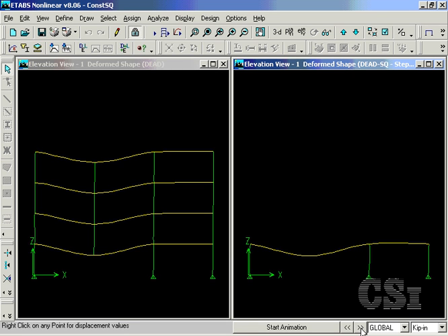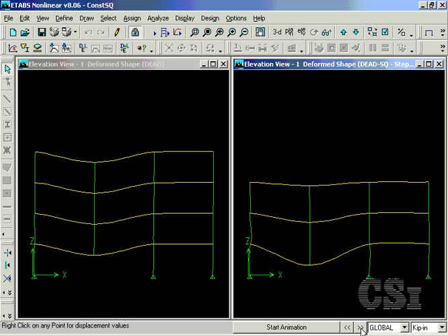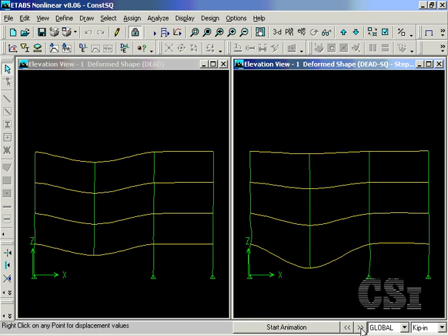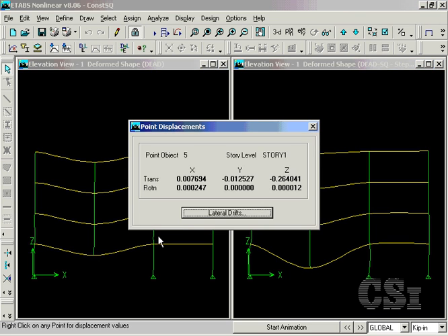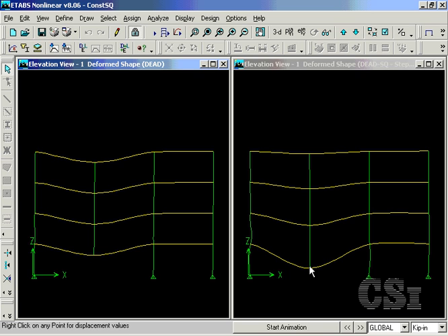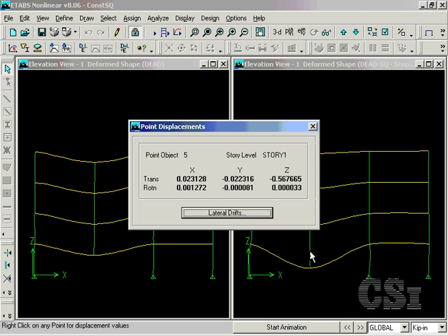Starting with step 0, the first floor undeformed, we can toggle up the construction stages. Note how the displacement at the transfer girder location grows significantly larger than that of the model where no sequential behavior is accounted for. In fact, a right click on the girder shows the displacement to be approximately 1/4 inch for the non-sequential case, while the displacement is more than double when sequential effects are included.